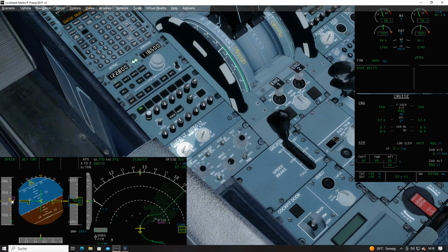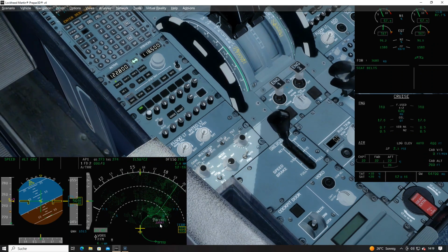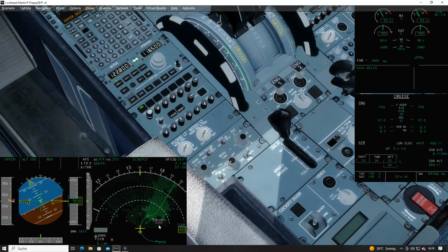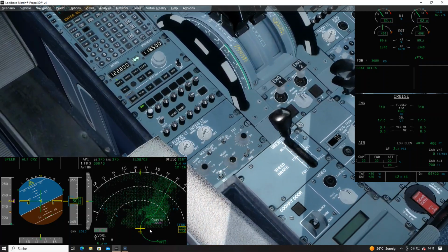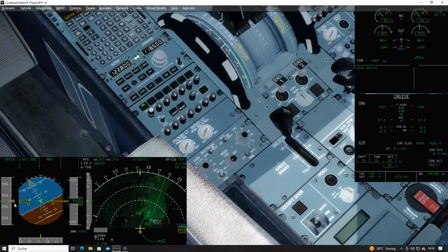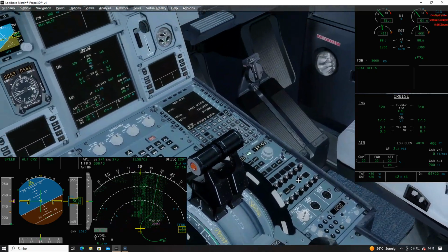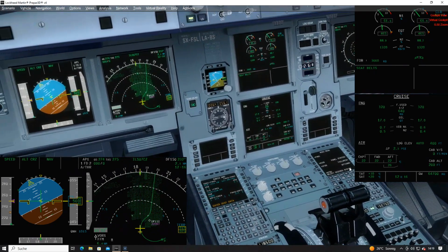Still accelerating. Now we've passed, looks like we've passed the first speed limit, however there's a speed constraint still of 220 knots, so this is a failure in the simulator. The speed constraint is still applicable because we're on the way towards Delta Fox 150 and this aircraft has accelerated to 250 knots, which is not appropriate. So what to do?